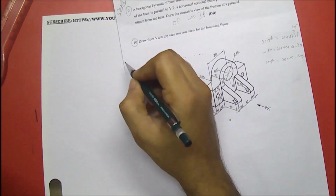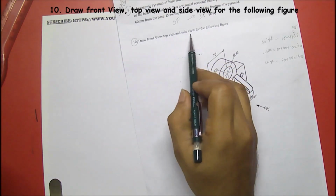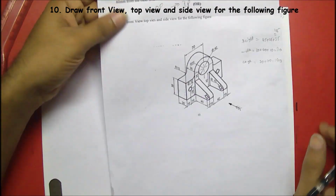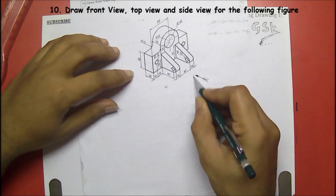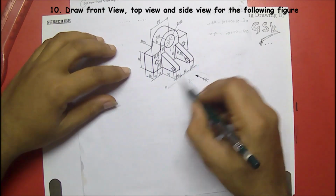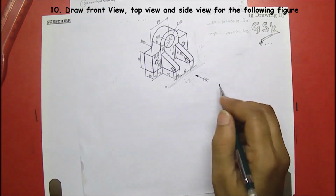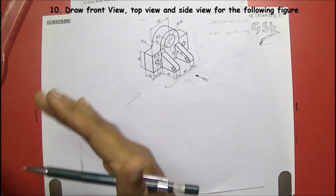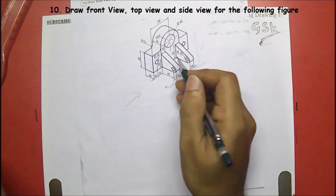Now we are going to discuss 10th problem. Draw the views, top view, side view, and the front view, right? So for this problem, I'll be considering this arrow mark indication as a front view, means here I can see the length and height and length. So coming to side view, because I'm looking from left side, that will be falling on right side. So left side will fall on right side for the first angle of projection.